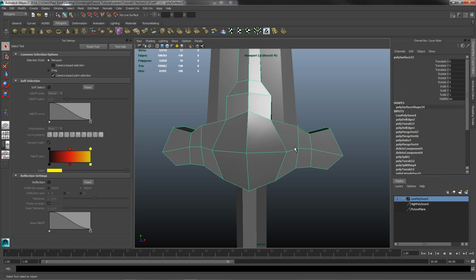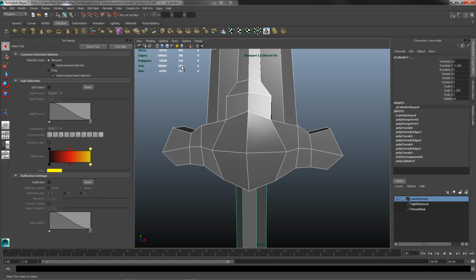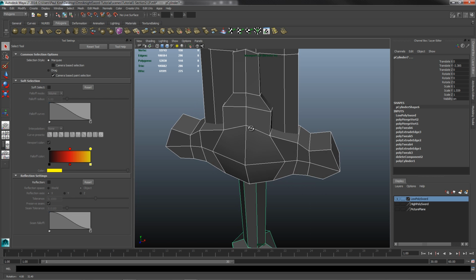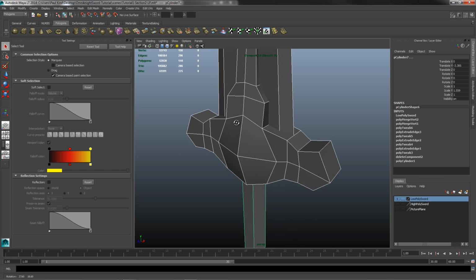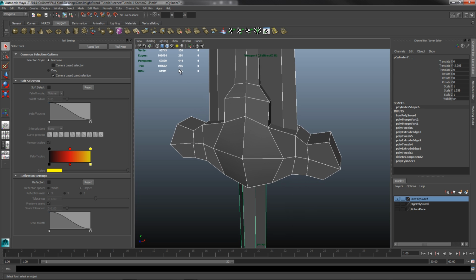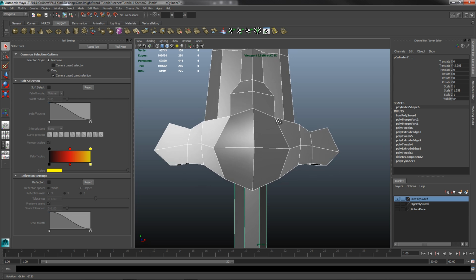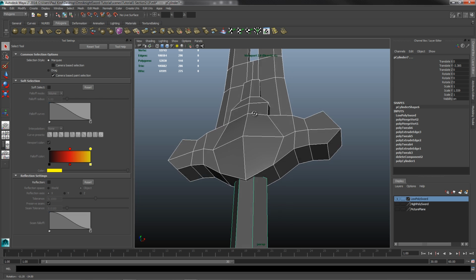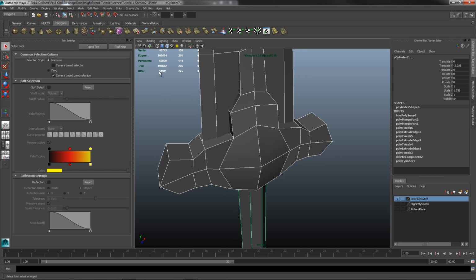All right, so to start beveling this, we really have to be careful of our poly count now, because we're getting kind of close. It's the triangles that we're really worried about. Okay, that's what the polys are going to mean. So when they're saying poly, they're not meaning a 4-sided polygon; they're meaning a 3-sided polygon. So each of our polys is actually two. So that's why we have, you know, double the number, and probably a few of them are merged in some places, but basically we're really worried about this triangle count, and we're getting kind of close.